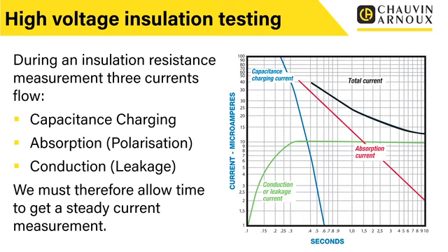So when we're carrying out these tests, we need to be aware that we have to apply it for a suitable time to allow for the capacitive charging, for the polarization, and for the conduction current or the leakage current to get to a steady state. And at that point, then we can take the readings.